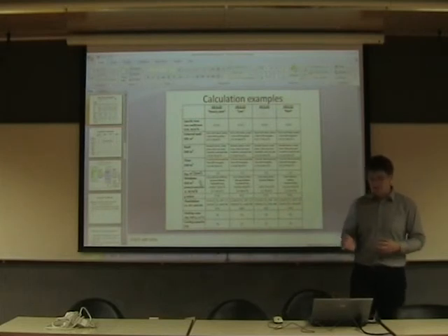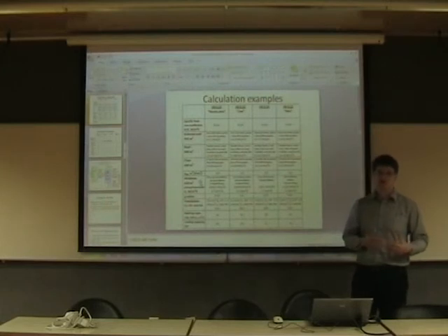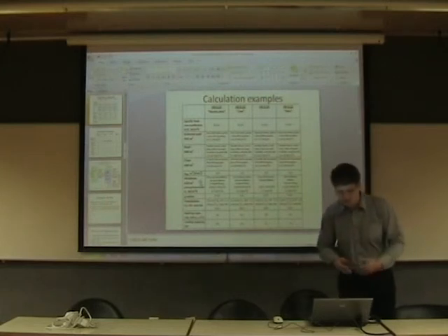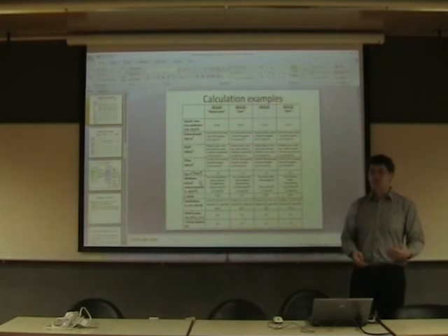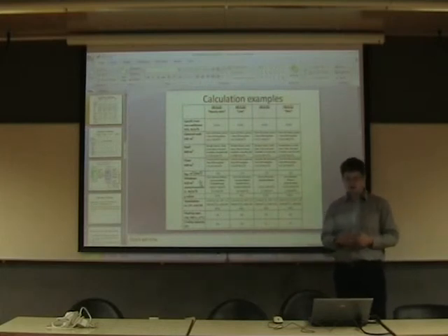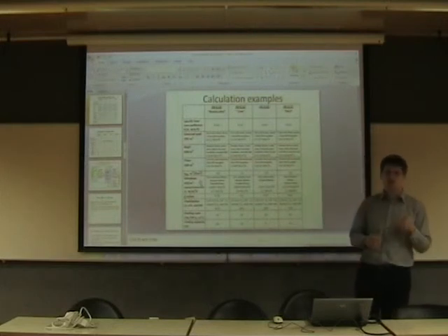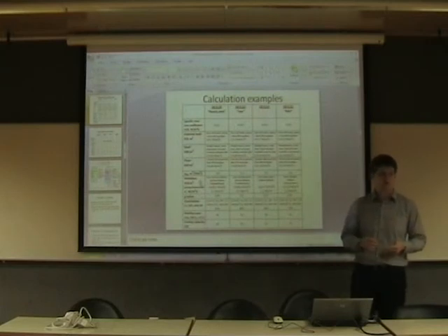Also, when you are making your renovation case, you must think about how we can cool down these areas after renovation, because this is the big problem. In Estonia we say that when we invest in heating houses, we put in like €1. But when we want to cool down, we put in 3 or 4 euros for the system. And it's a big amount of money.